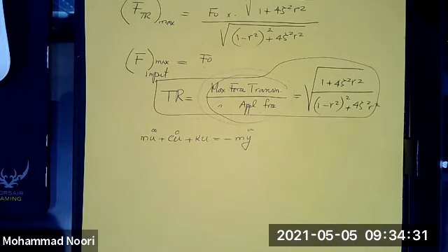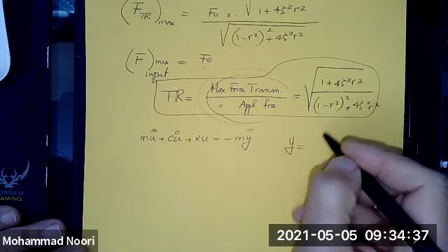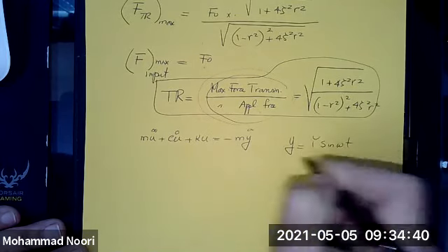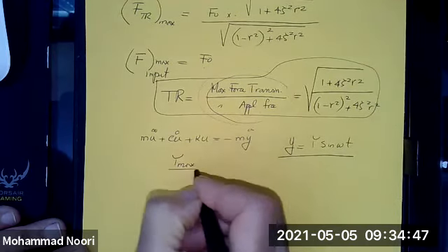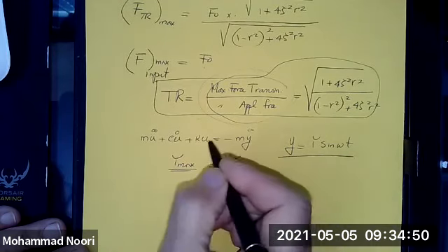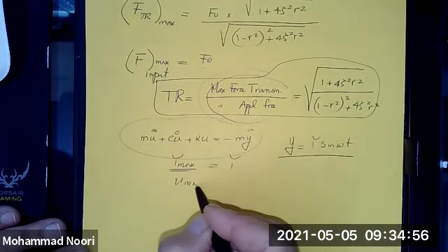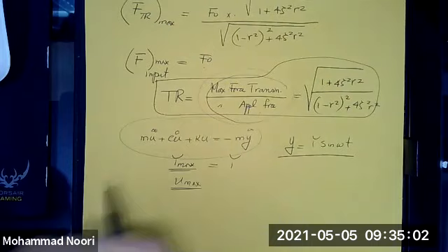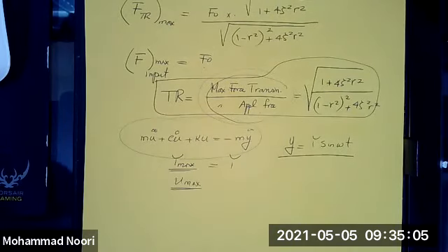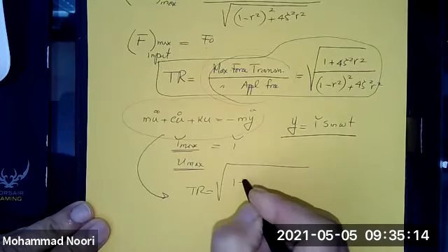You can see that even if you have an input displacement, and as long as the input displacement is of harmonic shape, so you find y max, the maximum displacement, which is u max from here, which you know what that is, F0 times H, you end up with the same transmissibility function expression.